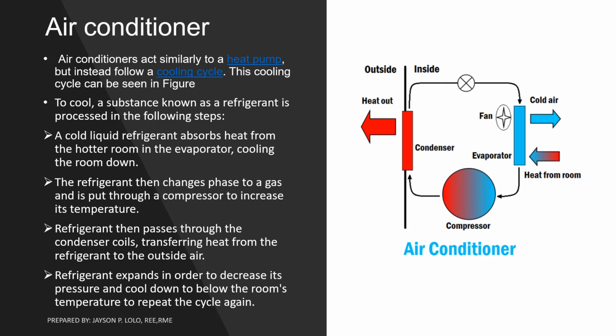The dehumidification happens as warm air from inside passes over the cold evaporator, where the warm air condenses and loses moisture, just like warm air does on a cold glass of lemonade. So that is just a simple scenario. The split system describes an air conditioner with separate indoor and outdoor components. There is also another type of air conditioner which combines these components into one outdoor system, known as a package system. I already attached this package system in the previous week.